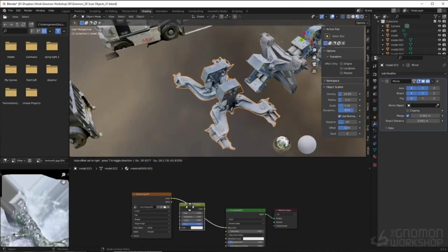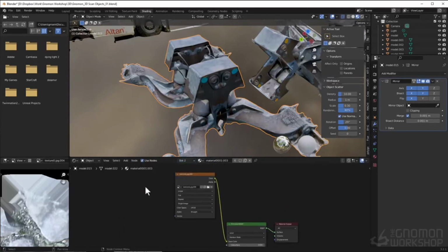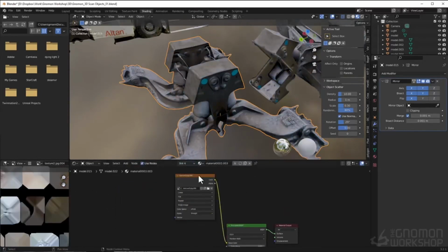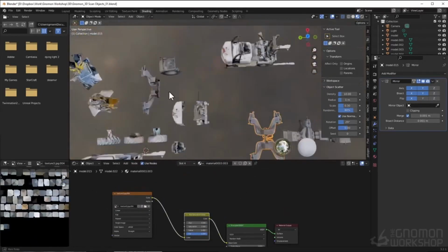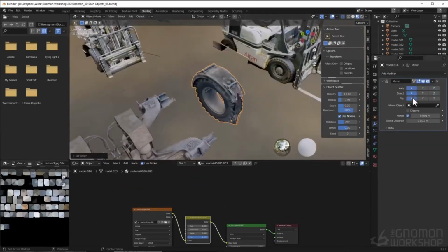I want the part to be a bit more yellow to fit the scheme I'm planning, so I add a hue saturation node to the base color texture. The way my scanning app works, there's 4 or 5 material slots that have the texture image separated out, so I just have to copy the node into each of them for the effect to apply to the whole object.